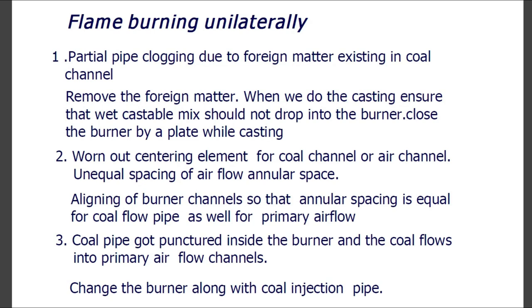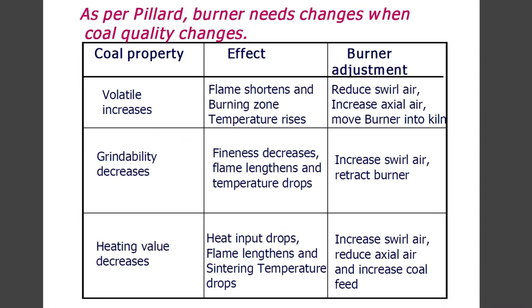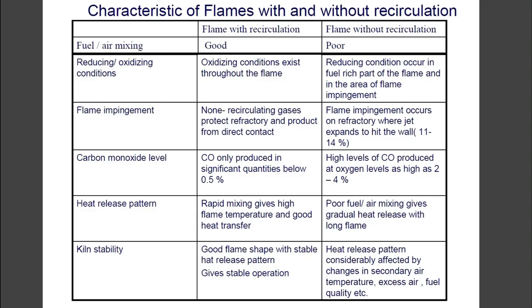Coal pipe got punctured inside the burner and coal flows into the primary airflow channels. Change the burner along with the coal injection pipe. As per pilot, a burner needs to be changed when coal quality changes. You can see here three columns: coal property, effect, and burner adjustment.